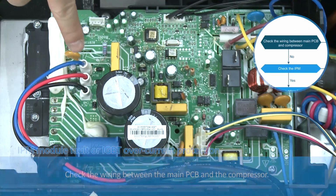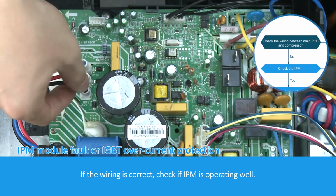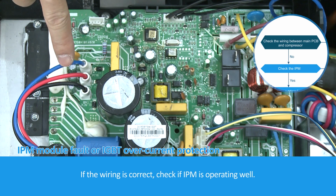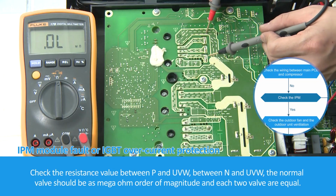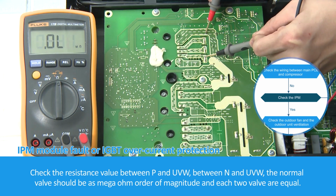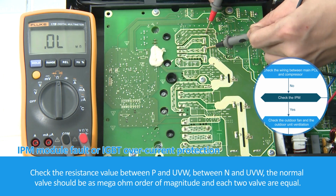Check the wiring between the main PCB and the compressor. If the wiring is correct, check if IPM is operating well. Check the resistance value between P and UVW, and between N and UVW. The normal value should be in the megaohm order of magnitude, and each two values are equal.